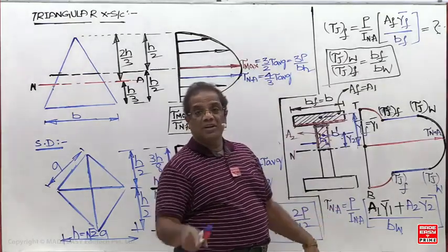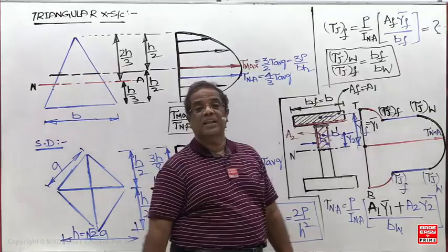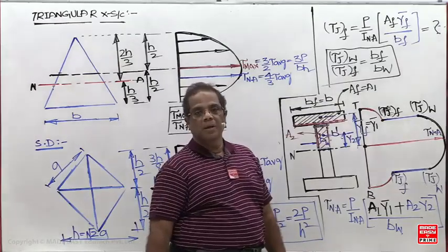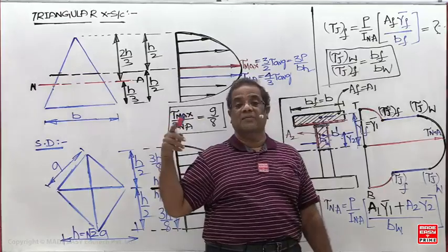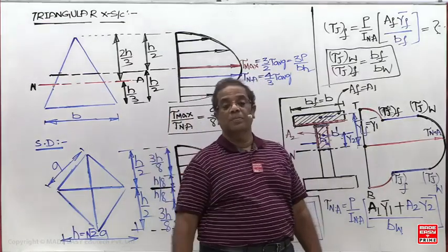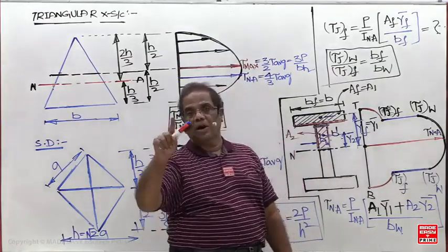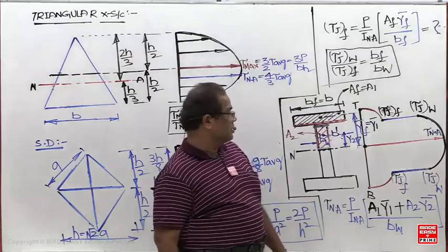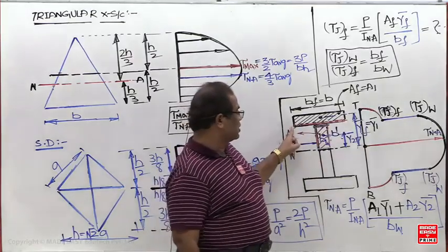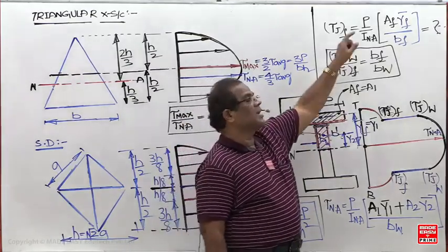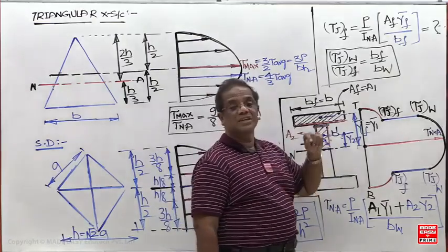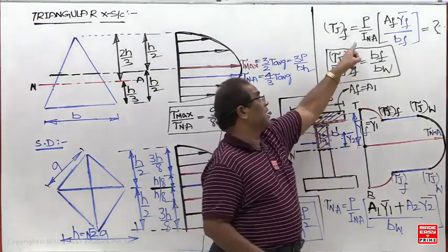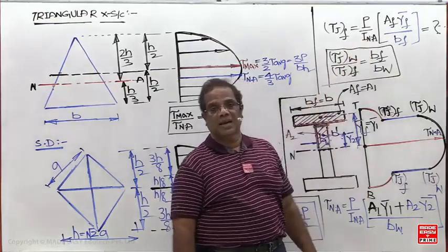So generally this is for conventional, but in the workbook I have given one question, that is a GATE civil engineering question. But in mechanical we mostly get questions only on the variation, or otherwise they are based on the constant. In the workbook one question is given on this, asking to find the shear stress here, so you can calculate directly. First you have to find the moment of inertia about the neutral axis. But in an objective question, they will directly give the moment of inertia about the neutral axis.